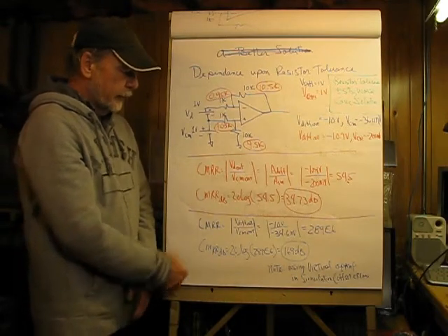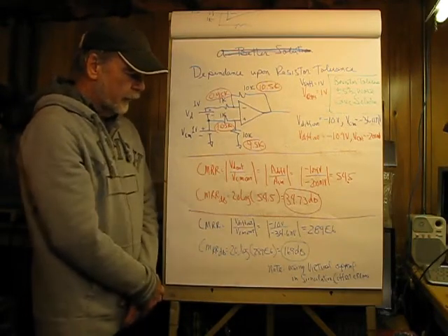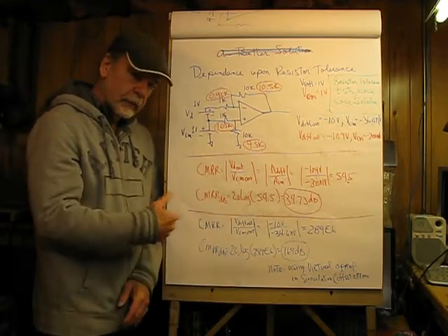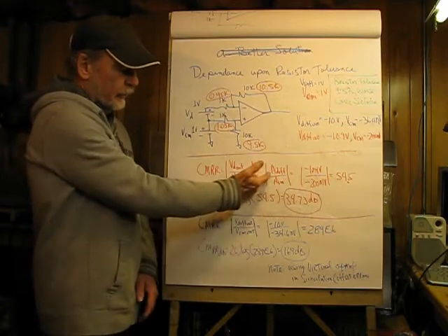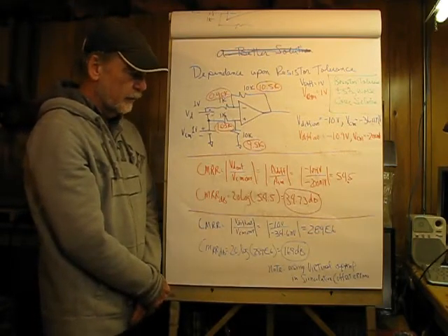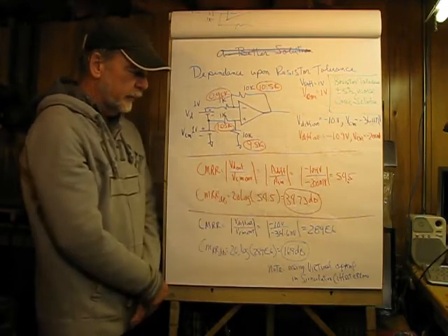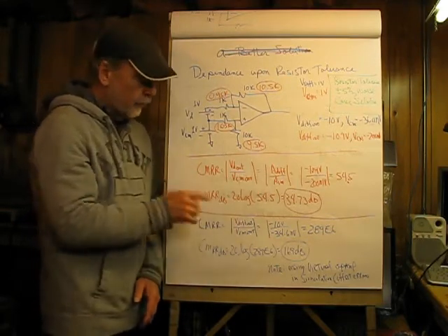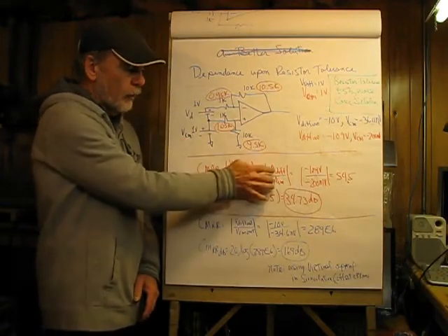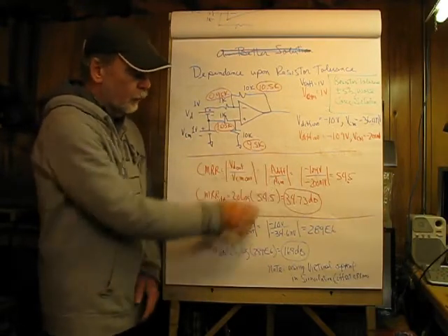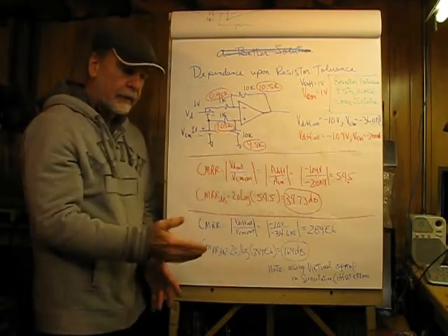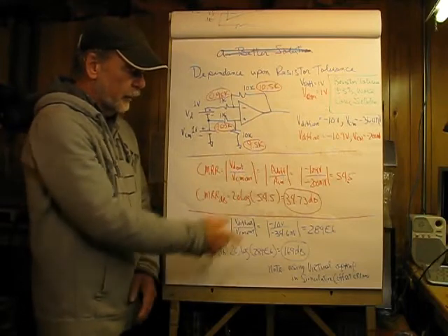To start with, it's simply the output differential voltage component divided by the common mode output component, which is basically equal to A diff, the gain of the differential mode connection, divided by the gain of the common mode connection, except the actual measured value includes the error. If we're working this off the intrinsic values of the blue up here, the ideal, then this will be off.